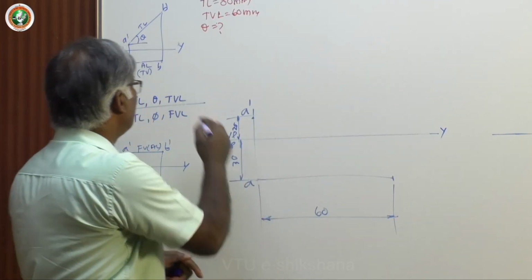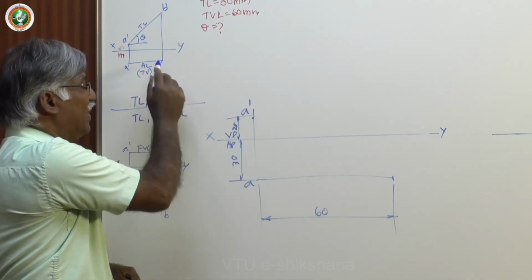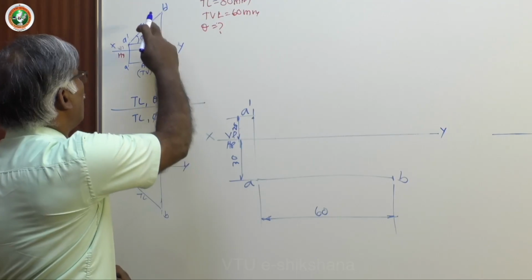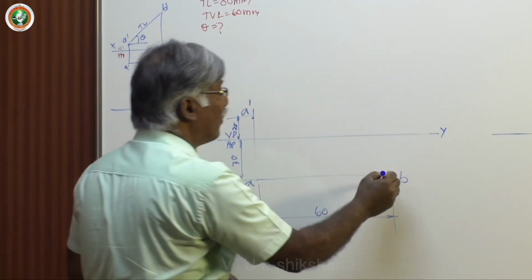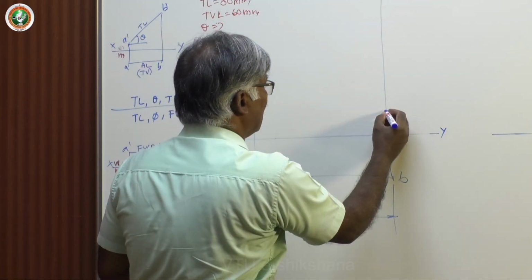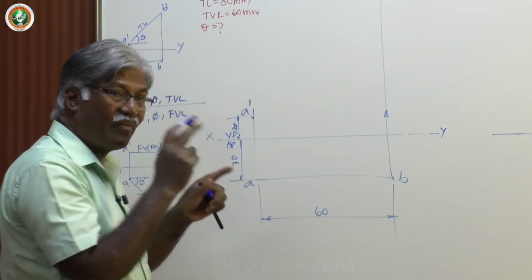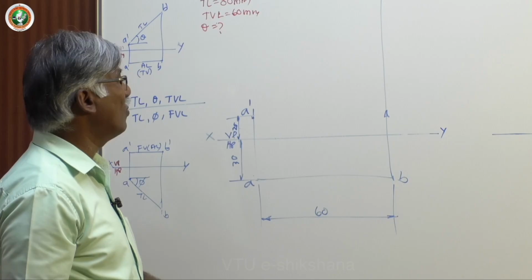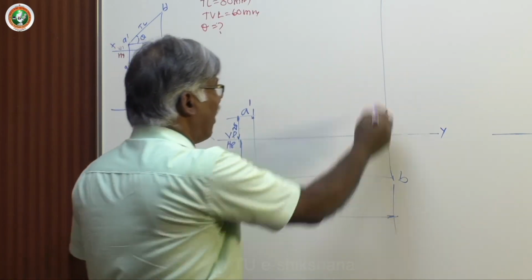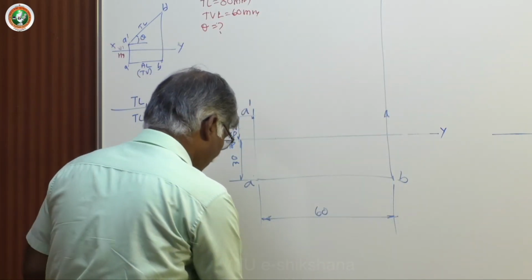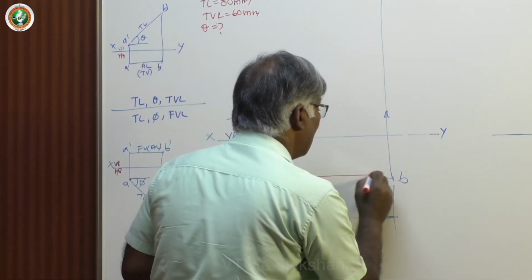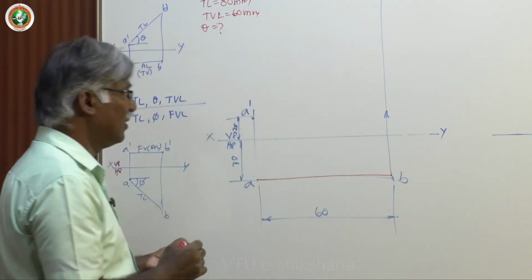Now just observe here, I have AB fixed in the top view. Then I have to fix this. Draw the locus, the vertical projector of B. A dash is on a vertical projector. Similarly, B dash must be on a vertical projector. So I draw the vertical projector of B, having the length fixed here.